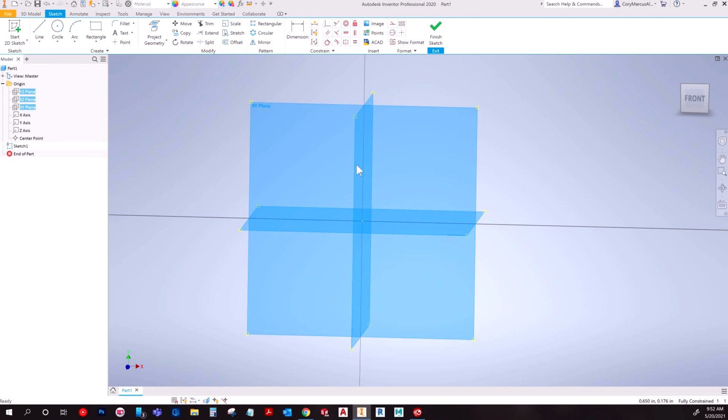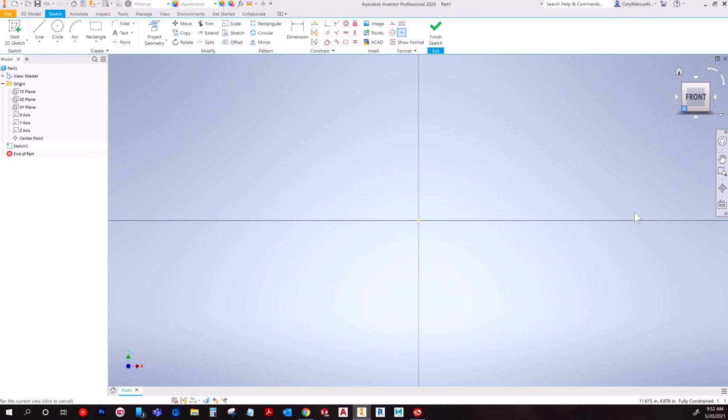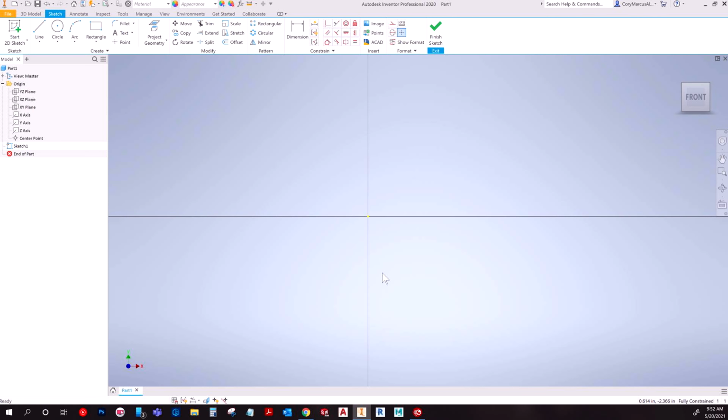You would have like a Cartesian plane. Well, consider this like your crosshair, and basically you're going to want to always draw things in reference to this origin point for two reasons. I won't hunker down too hard on it in this first video, but basically you're going to want to fully constrain parts. And if you notice down here, there's that phrase right there, fully constrained.